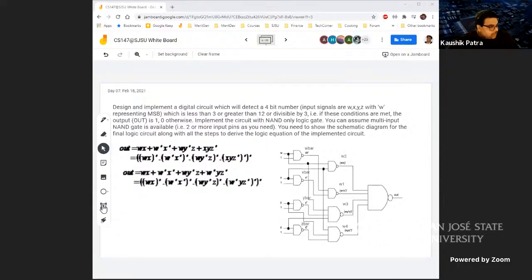Really, if some of these internal logics, let's just name them as a wire, right? This W2 is basically W and X NANDed, so we are taking W and X and making it bar, through the NAND. For this one, we can write an instance name, N8 for example, followed by a NAND.